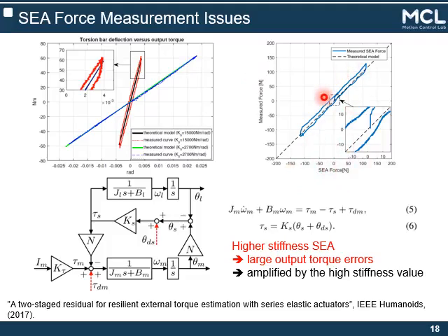So this is a very significant problem when SEA force information is fed back to the controller with high gain. This hysteresis can even deteriorate the feedback stability, which explains why the performance of the force control is limited when a high stiffness spring is utilized.